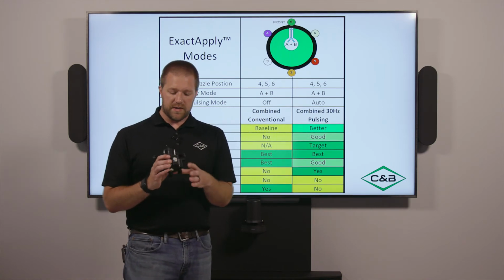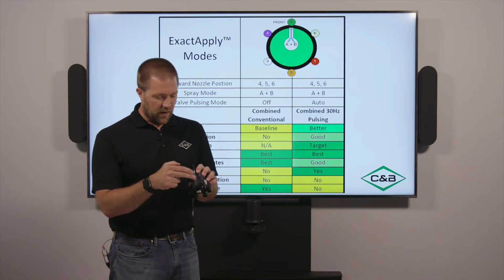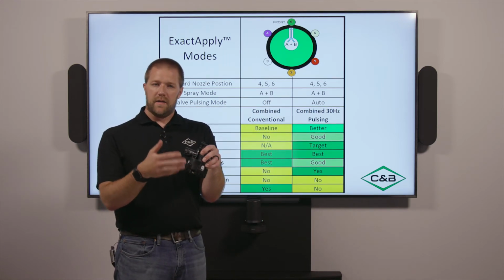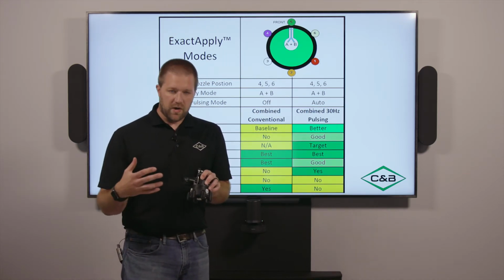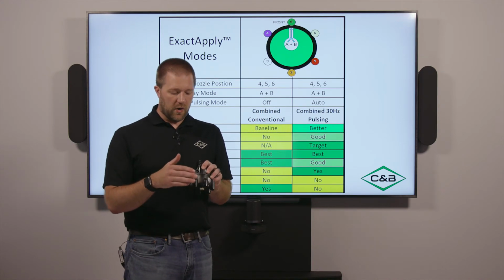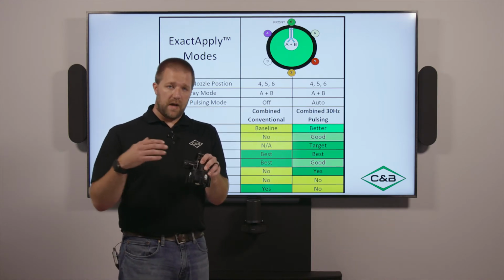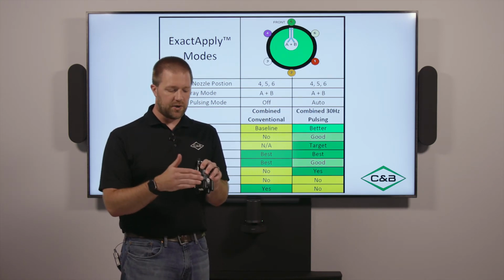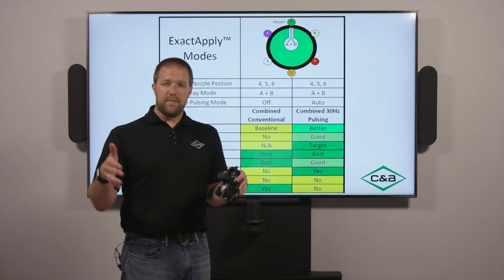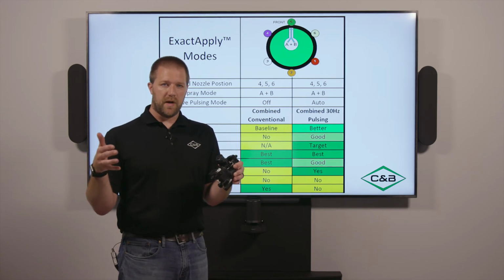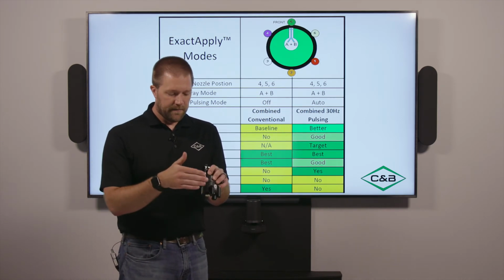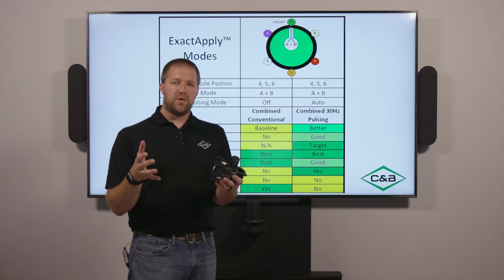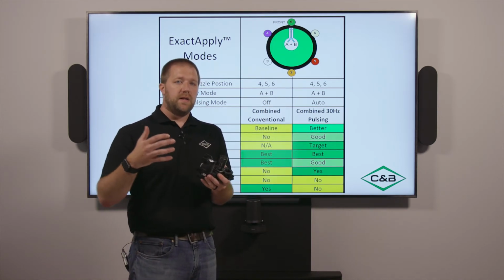Okay, so with AB Auto Select, say I had an 04 nozzle on the front and maybe an 06 or an 05 nozzle on the back, and they're air inducted. When I first start a field, like we showed in the video, it might start on the front nozzle, and I'm operating at a lower speed. If I hit a threshold, say 40 pounds of pressure, that I can't exceed based on the label or because the droplets are getting too small, we can have it automatically switch to the back nozzle. So we go to a larger nozzle and lower the pressure again, which allows us to increase our speed a little more.